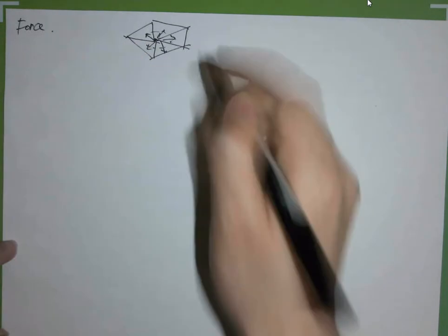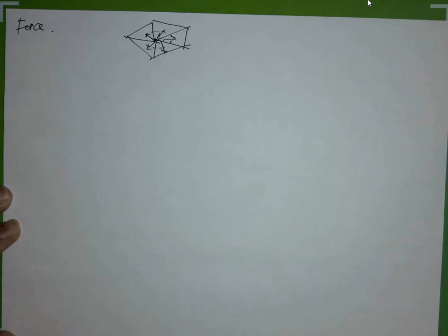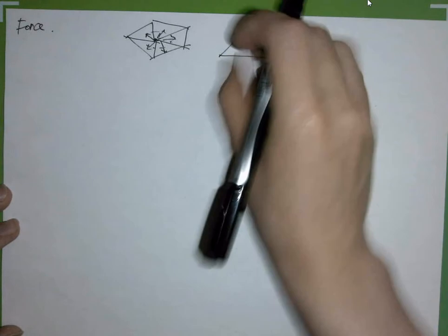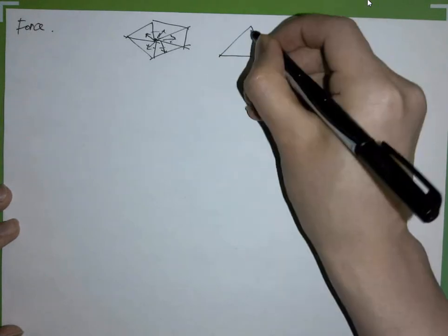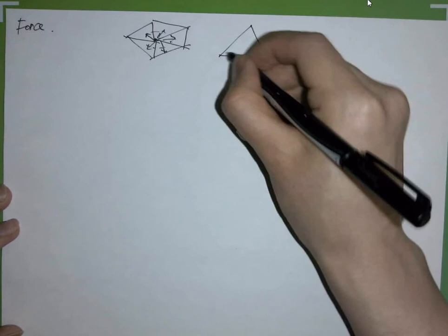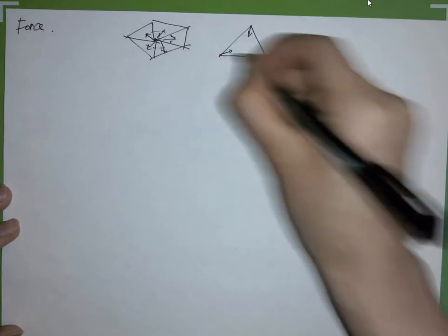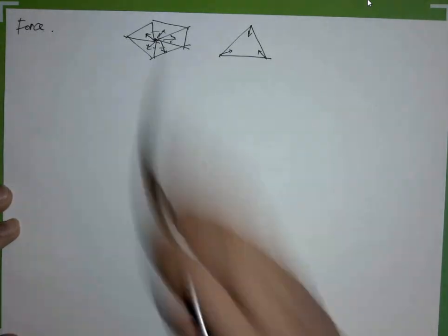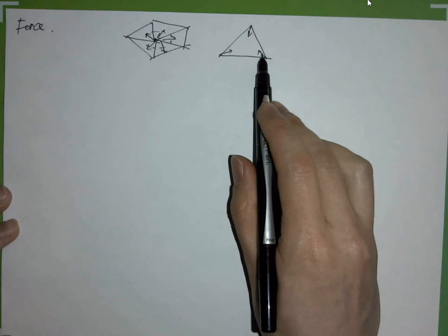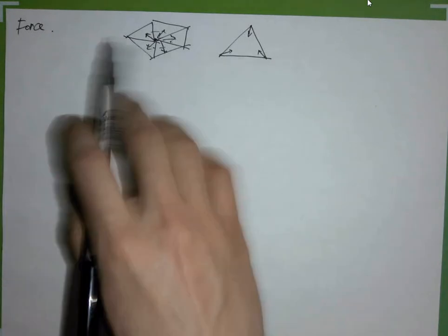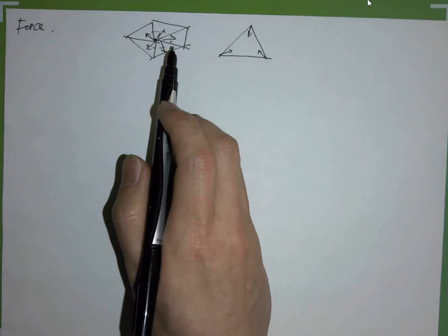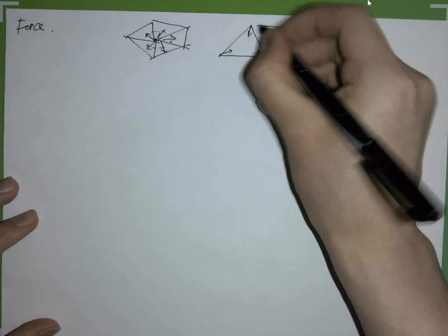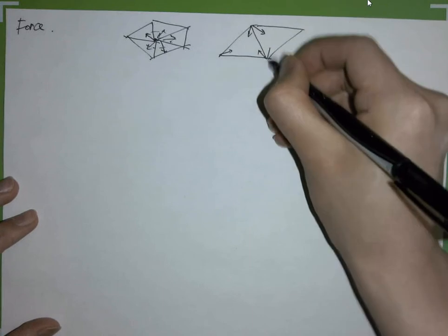But we can also see it in a per-element, or element-wise view. If I have an element, and this element has been extruded a little bit, we can think of this element as pulling all three vertices inside a little bit. And if we go over all those elements and add the forces on the vertices together, then we have the force on each vertex. Like the other element is pulling those two vertices over here.